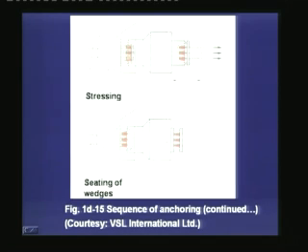The jack applies the load as the piston moves this anchorage block outside. Once the required amount of tension is applied, the double acting jack applies a push to the anchor block on the left, which helps to seat the wedges inside their sockets, and finally after this operation is done, the extra amount of the tendons are cut and the jack is taken out.